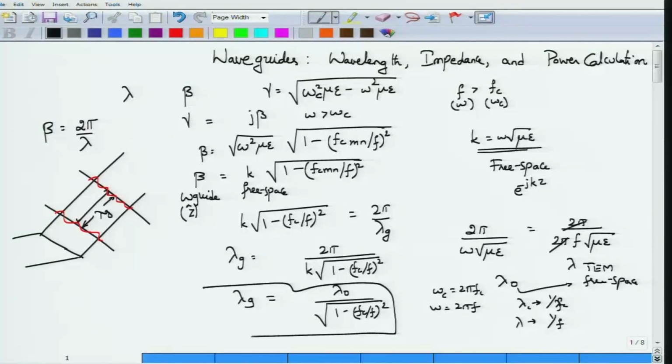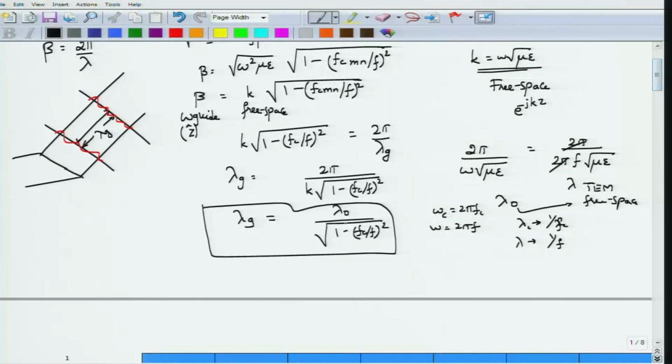What is interesting is that the guide wavelength that you have obtained is actually greater than the free space wavelength lambda 0. So, if you were to plot this guide wavelength as a function of frequency, so the wavelength in free space, this is how it would go. At f equal to 0, the wavelength would be infinity, and thereafter it is a 1 by f kind of relationship. The ratio of these two at any given point would give you the free space velocity as well.